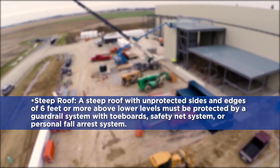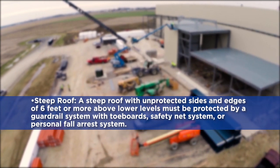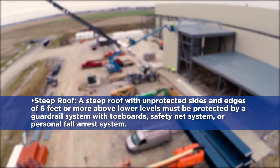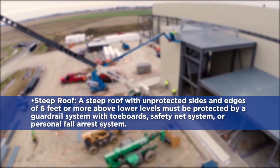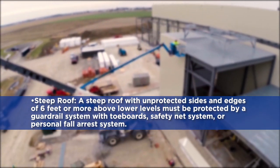Steep roof. A steep roof with unprotected sides and edges of 6 feet or more above lower levels must be protected by a guardrail system with toe boards, safety net system, or personal fall arrest system.